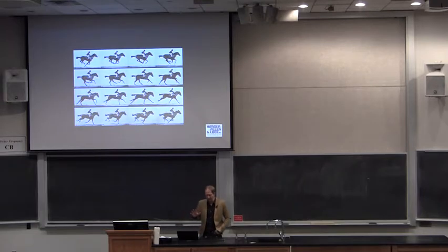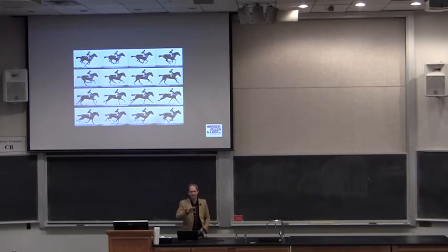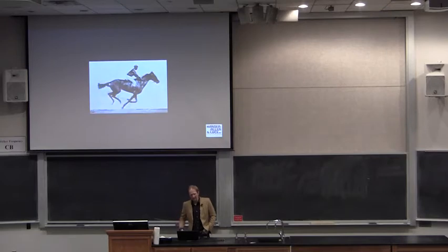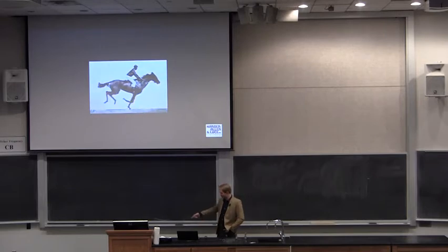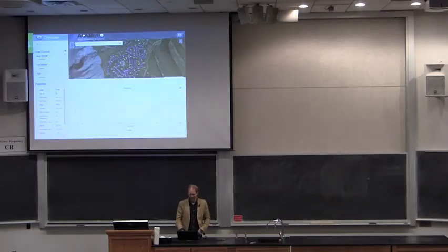Extended period modeling is more like a movie. A movie is a set of still shots put together and then played back to show motion. And so that's kind of how the hydraulic model works. It's a set of static models put together. So you take a static model, and then you run it, and then you take the results and run it again at the next time step, and then again and again. And then once you've done that, you can play it back so that you get a sense of the system working. So you can see the tanks filling and emptying. You can see the water where it's going into the system, and that gives the operators and the engineers good confidence that the solutions are working.